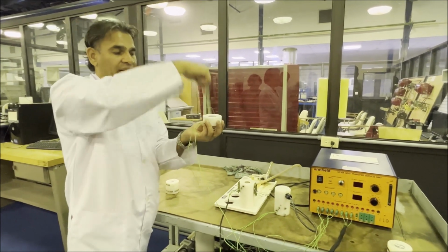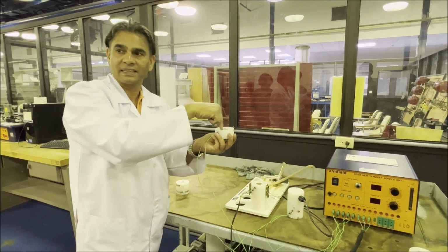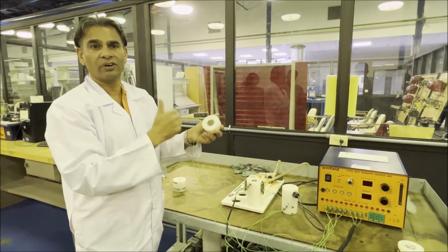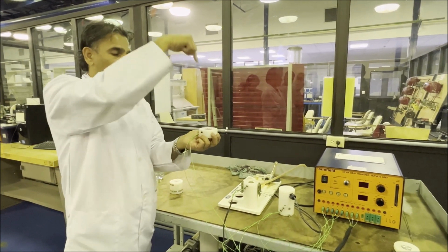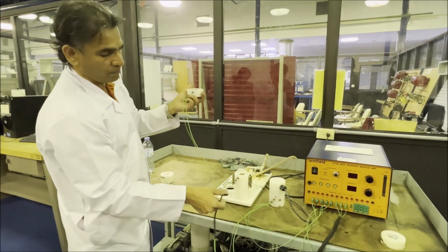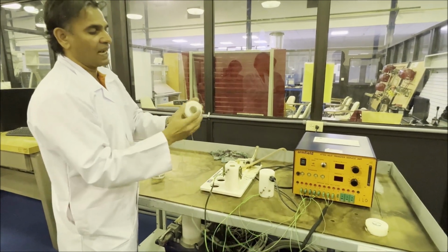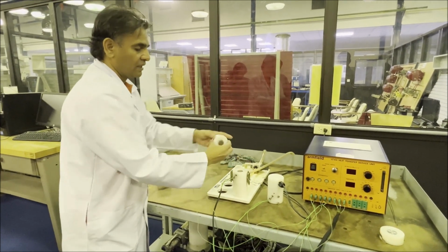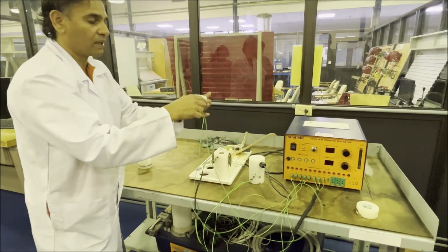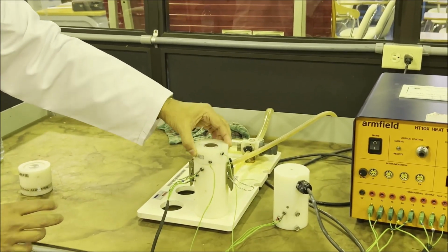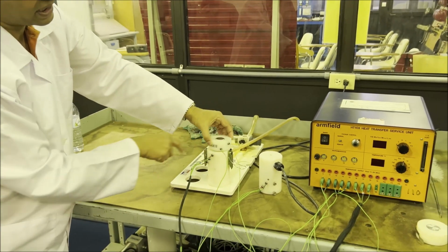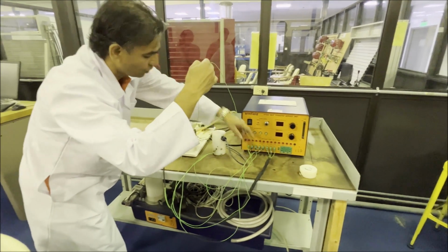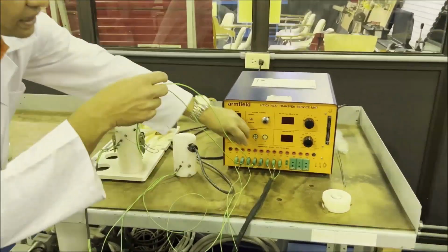So I know diameter, I can find out area because heat is flowing like this. This dimension is given to you in the lab manual or in the question. We need to find area. So cross flow area is this. So this thermocouple and this thermocouple, and there is a slot here, projection and slot. So check. If you put like this, it will not fix, but put like this, yes. So this projection will go inside the slot like this. Okay, now this thermocouple is connected to 4 and this thermocouple is connected to 5.